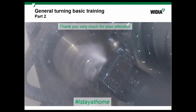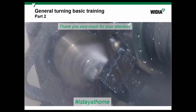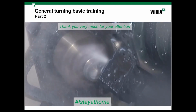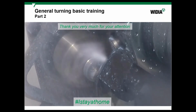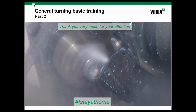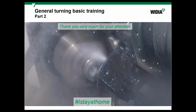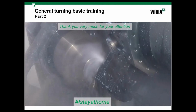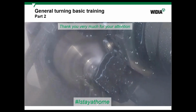If tool life is not enough, you look at the wear type. Is it a brittle wear type, I mean chipping, or an abrasive wear type like flank wear? You can change this grade, in the first case to WP35, and in the second, when it's abrasive wear, to WP15. But usually the first choice is the same as for all turning inserts.